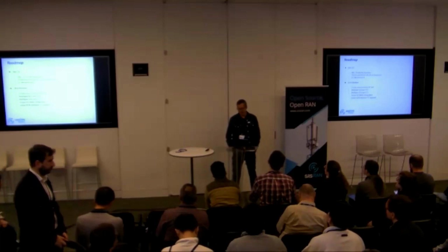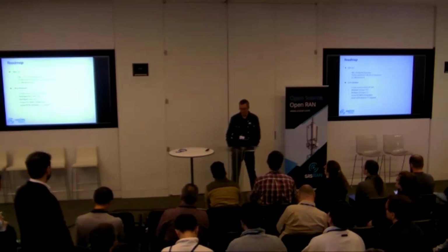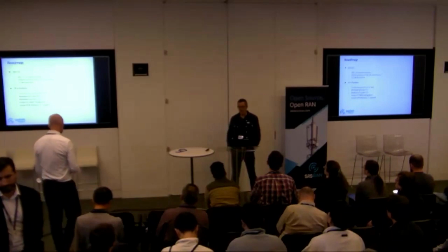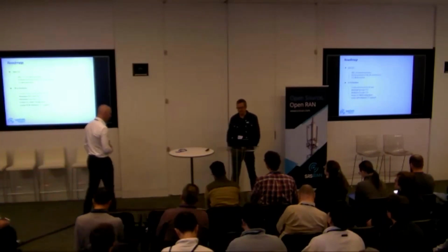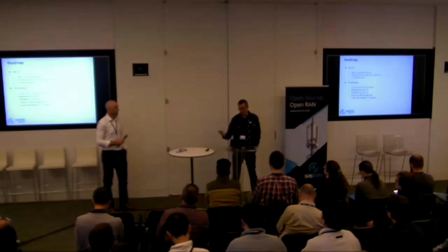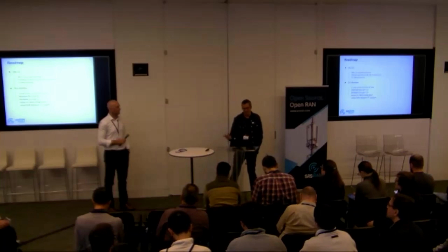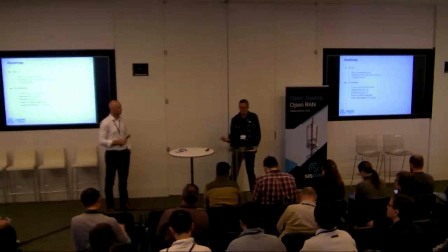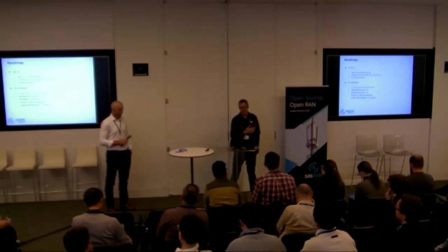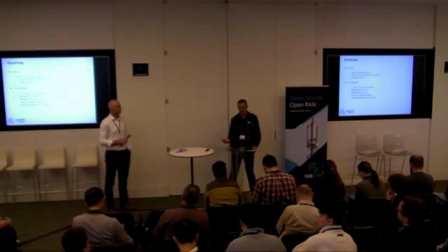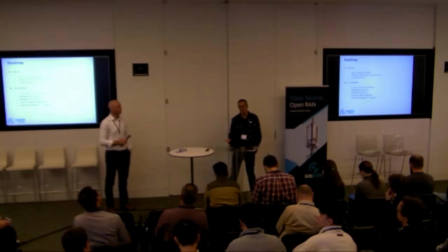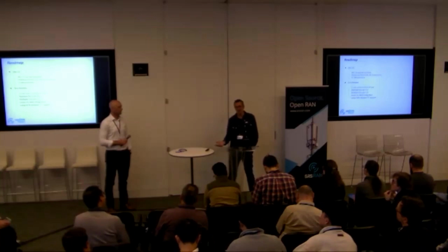There is no plan until the next release to provide beamforming. I guess that at the current private 5G market that we are addressing, that only uses 4x4 RUs, doesn't make a lot of sense. Certainly when we go to FR2 or higher order of antennas, then beamforming, I guess that in the RU will be the next big topic.